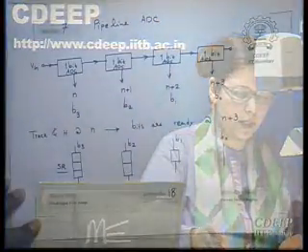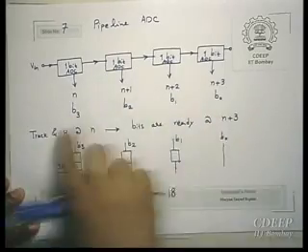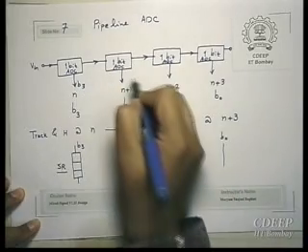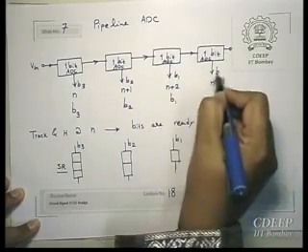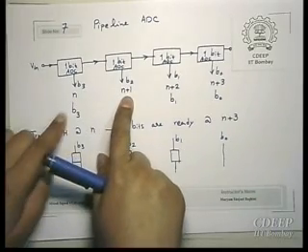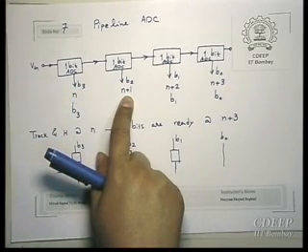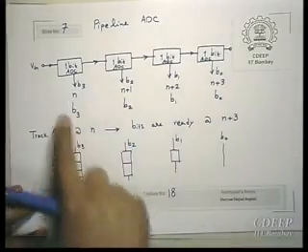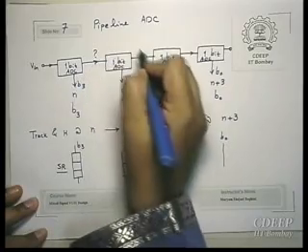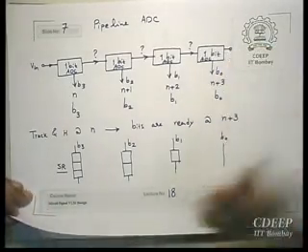But how is this done, and mathematically, what is the output? For example, here the vertical outputs are of course the bits, B3, B2, B1, B0, and this is for these cycles. Now, if you go to n plus 1, when you are at n plus 1, instead of B3 you will have B0 of the next sample, and so on. So this is a pipeline kind of architecture. Now what is this output? What goes from one stage to another stage? And eventually we may not need that output.